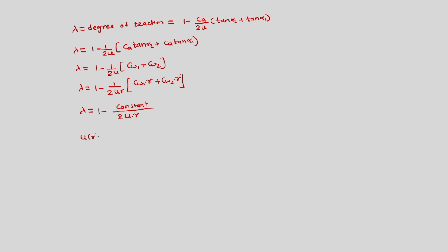So this u at some R is equal to pi into twice R into n divided by 60, and we can represent it if we know um, the mean blade speed at mean radius, which is pi twice Rm into n divided by 60. Let us divide both the terms. Then we have u at any R divided by um at Rm is equal to R divided by Rm.